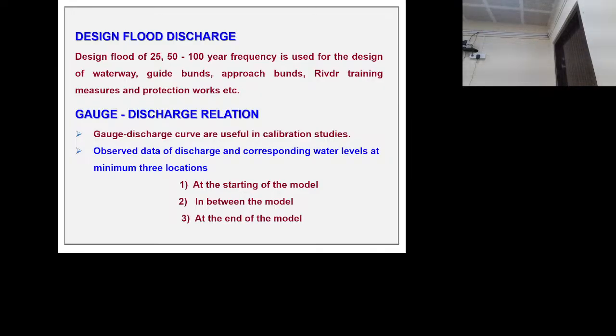Now it will be revised to 50 years. It depends upon the location also. This 25 years we will take for agricultural lands, forest areas like that. 50 years for nearby agricultural lands, and 100 years for cities like Surat, Delhi. Now we are proposing 100 years for flood protection works.